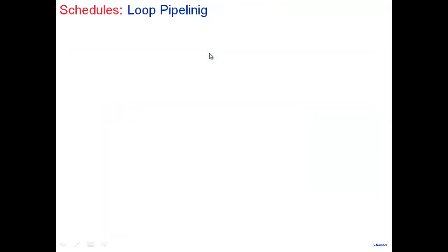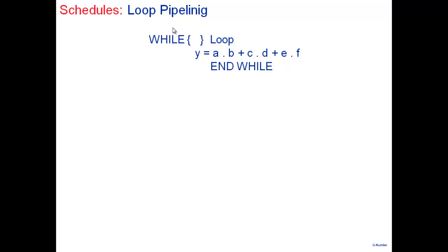The other one is the concept of pipelining. Pipelining was that when you give data to an input, don't wait for the system to process that particular input completely and then produce an output and then give the next input. The idea is to break the processing into several parts. One part may be processing data which is xn, another part may be processing the data which is xn minus 1 in the previous clock cycle, and the third part may be processing the data from the clock cycle before that. The advantage was, yes, latency may remain the same, but the throughput will increase. So in this case, we are talking about pipelining the loop.